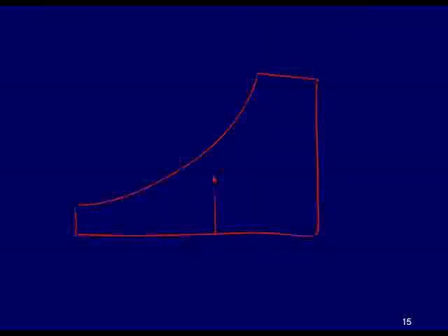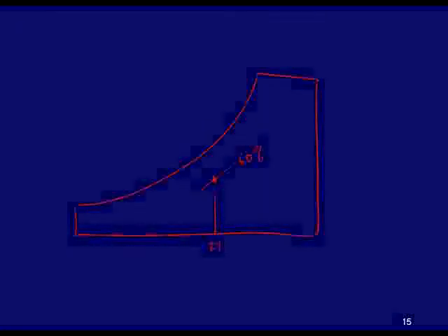I'll draw it for you. Here we had state 1, 27 degrees and 60% relative humidity. State 2 was 10 degrees and saturated, along the saturation line. So when you mix them, the resulting mixture is going to fall on the line between those two.